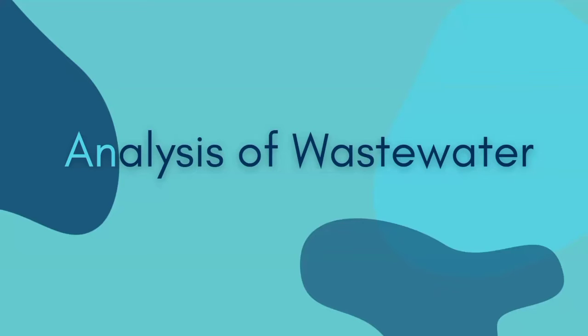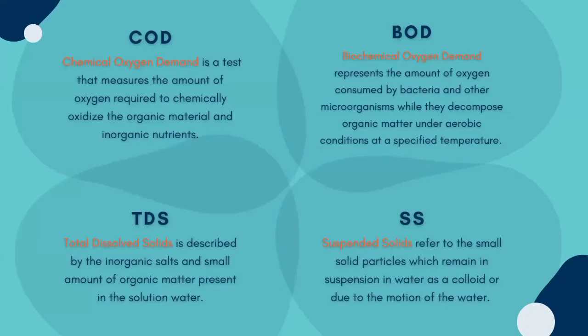The analysis of wastewater was carried out for pH, BOD, COD, TDS, SS, chlorides, sulfates, etc. COD, also known as chemical oxygen demand, is a test that measures the amount of oxygen required to chemically oxidize the organic material and inorganic nutrients. BOD, also known as biochemical oxygen demand, represents the amount of oxygen consumed by bacteria and other microorganisms while they decompose organic matter under aerobic conditions at a specified temperature.